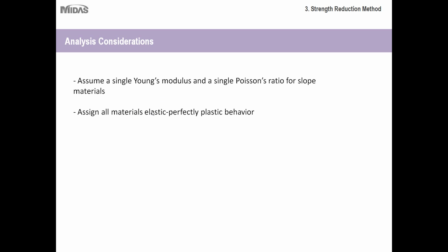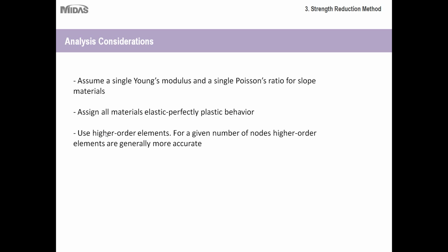I'll assign all materials elastic perfectly plastic behavior. That's pretty straightforward. Obviously, if you want to calculate the deformation, it's really important to assign this type of behavior. And then use higher order elements. For a given number of nodes, higher order elements are generally more accurate.